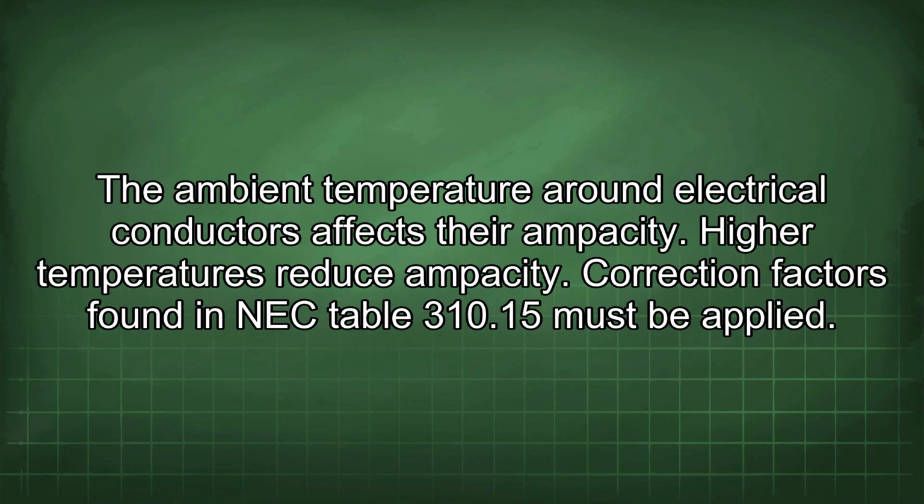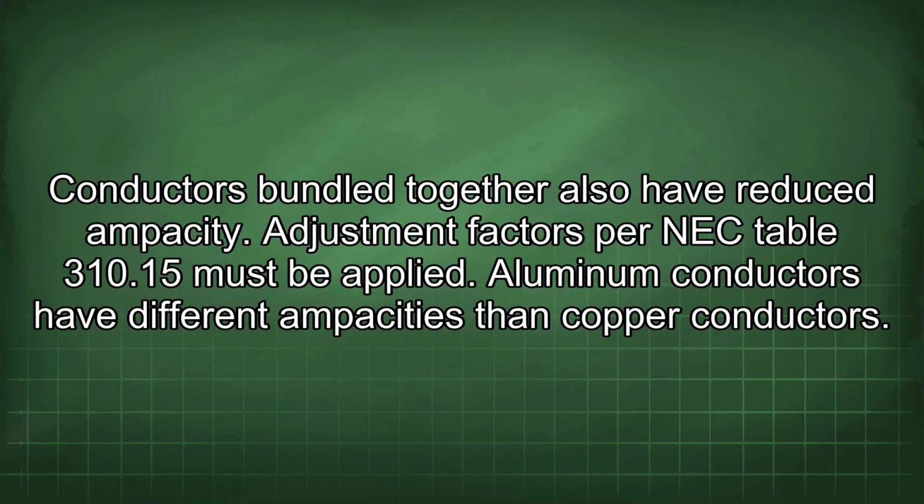The ambient temperature around electrical conductors affects their ampacity. Higher temperatures reduce ampacity. Correction factors found in NEC Table 310.15 must be applied. Conductors bundled together also have reduced ampacity. Adjustment factors per NEC Table 310.15 must be applied.